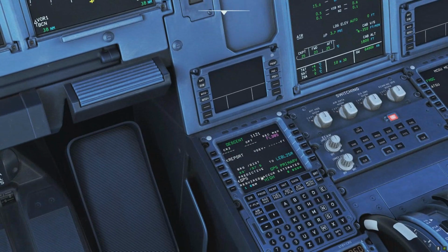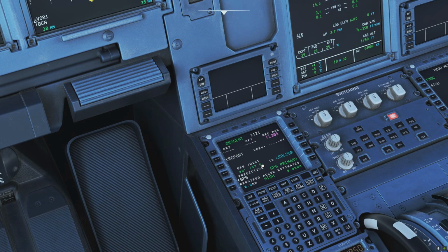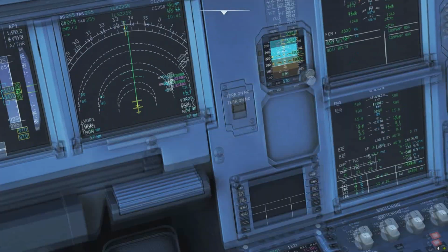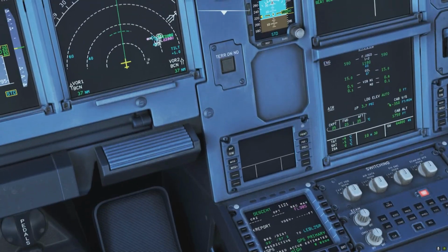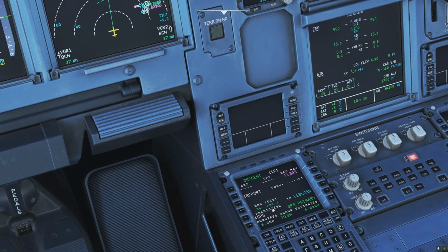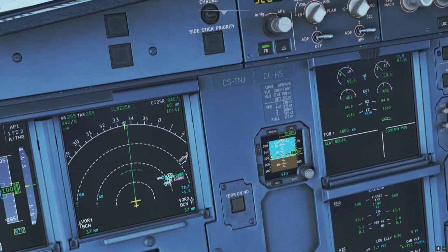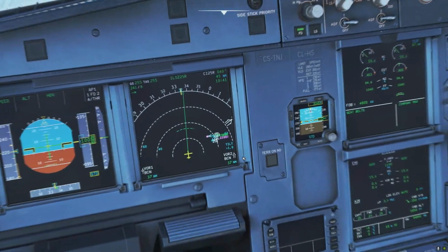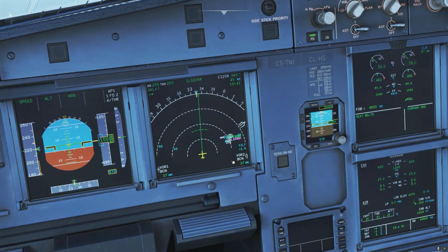So the aircraft tells us we're about 30, let's call it 35 miles away from the threshold. We add another 20 miles because we're going to need 10 outbound, 10 inbound. So let's call it 55 nautical miles to the runway, and here it says we're going to need 30. We don't need to slow down anymore, so we're still very good in terms of profile.